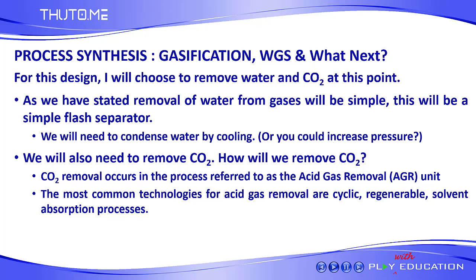We will also need to remove the CO2. How will we remove the CO2? CO2 removal usually occurs in the processes that are referred to as acid gas removal in the industry. They are called AGRs. The most common technologies for acid gas removal are cyclic, regenerable, solvent absorption processes. We will just quickly, briefly look at those, just to give you an indication of what these technologies are.